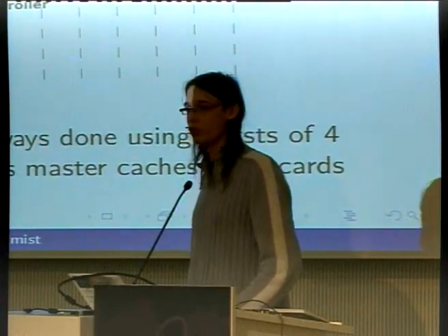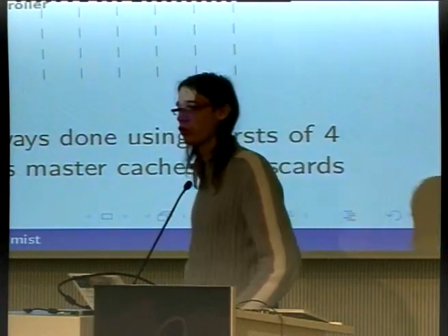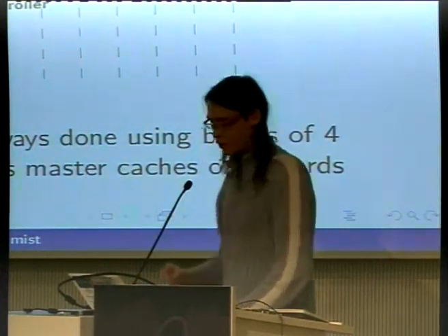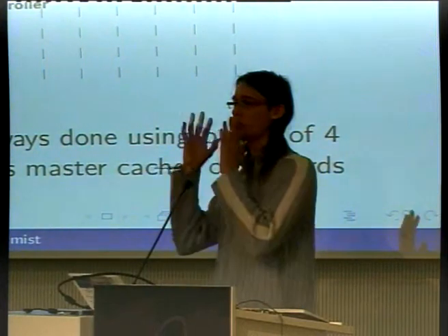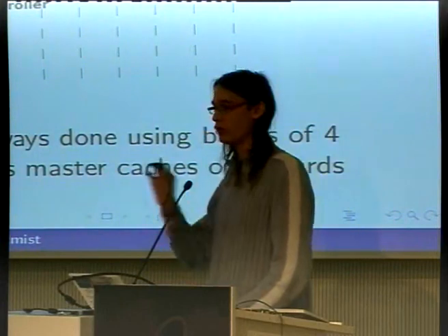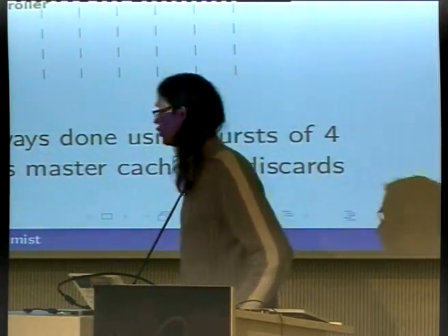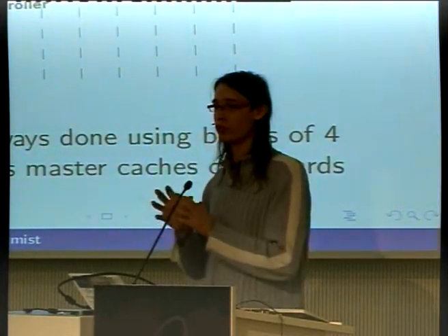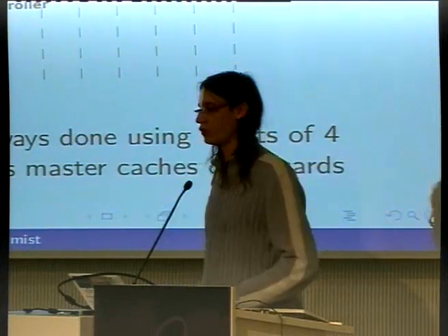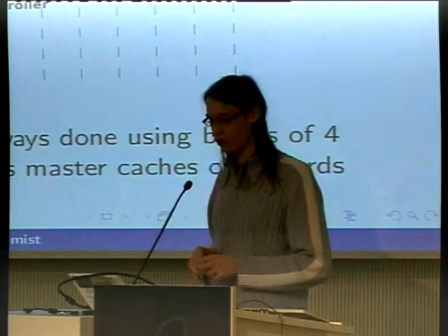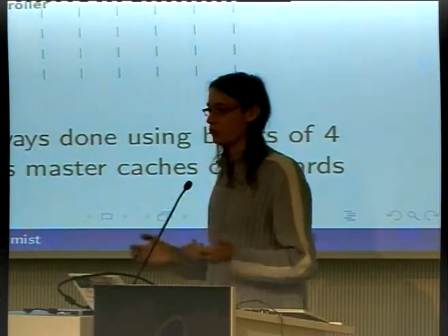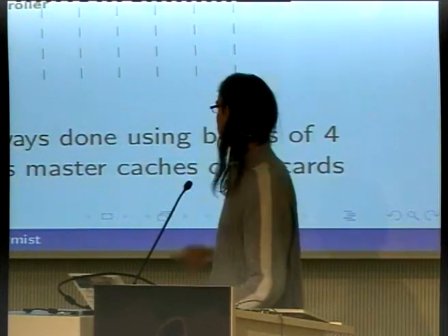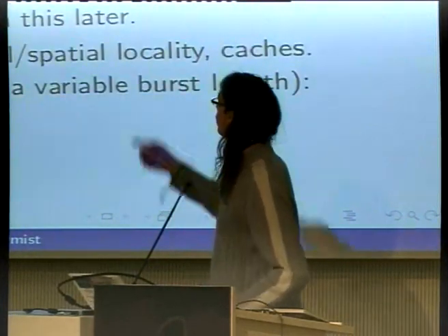But what you can do, which is a much simpler solution, which doesn't need an out-of-order CPU, is do something which is called bursting. Every time you do a memory transfer, you get the first read command, and then you read the consecutive words. And in Milkymist, I am using a burst of 4 words. So every time I request any word from the memory, the controller automatically requests the next 3 words. I will then discuss how it could work, because it may seem a bit strange to do that, because you're not even sure if you're reading the next word or not. But I will discuss that later. So let's see if it's a good idea.